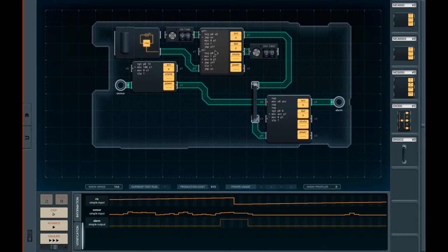So basically, we're just swapping back and forth between on and off states, waiting for the time to be equal to these things. Once it's equal to this guy, we switch to on. Once it's equal to this guy, we switch to off. You can't test greater than, because this thing wraps, right? I can't say, hey, is the time greater than or equal to 93, because between 0 and 20 is also a valid on time. And you can't test that we should switch off by saying greater than this value, because this is greater than this value and it is within our valid range of on time. So we have to kind of do something like this.